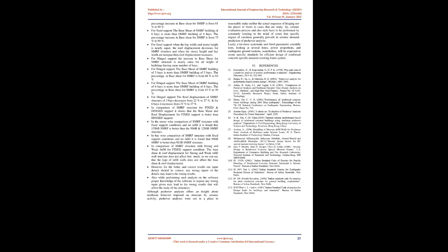In comparison of SMRF structure for fixed and hinged support, it shows that the base shear and roof displacement for fixed support is better than hinged support. In the story-wise comparison of SMRF structure with fixed support conditions and no infill, it is found that 15S6B SMRF is better than the 9S6B and 12S6B SMRF structures.